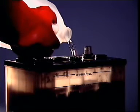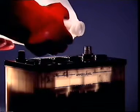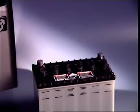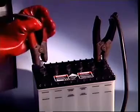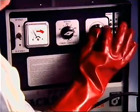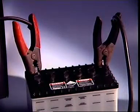The cells are sealed from each other and filled with dilute sulfuric acid. The battery case is usually plastic or hard rubber. One set of plates is connected to the negative side of a DC source, and the other to the positive side. Direct current is applied to the plates, changing them chemically until the battery is ready for service.